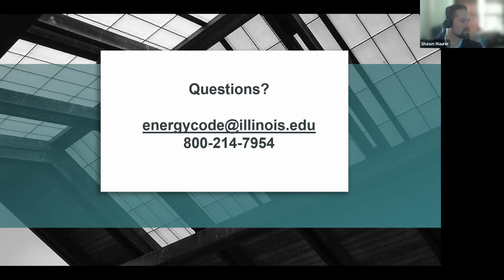We had a question here about whether you need to test an existing commercial building with changes in occupancy to a residential type structure. So changes in occupancy usually require full compliance when they are going to increase the energy consumption of the building. So it gets a little tricky trying to figure out, is this change in occupancy going to increase the energy consumption of the building, which would then trigger full compliance. Yeah, when you go from commercial to residential, that's also a trigger for full compliance.